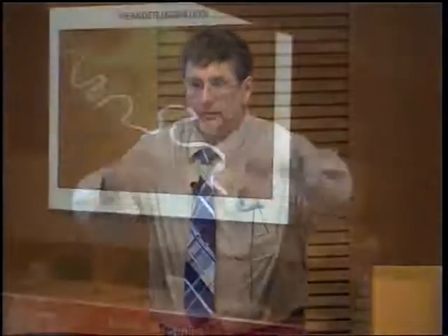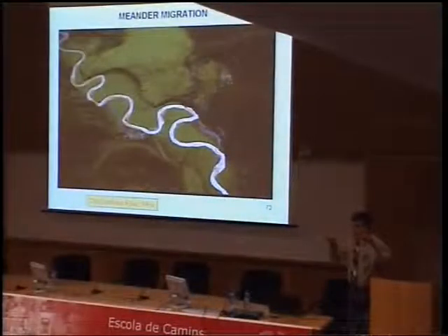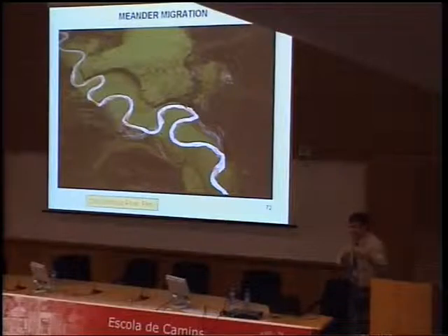I won't go into details, but the type of model we have put together assumes that as we erode a bank, slump blocks of vegetated sediment fall in, protect the bank until they decay. We furthermore assume on the inner bank that vegetation tries to grow inward on the point bar, but that vegetation is restricted the larger the shear stress associated with flood flows are.